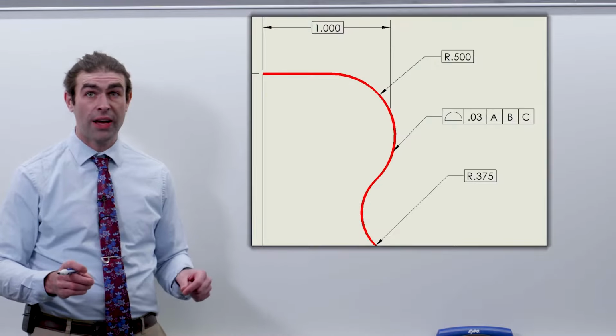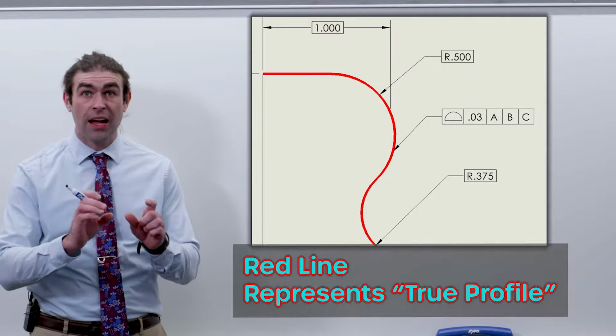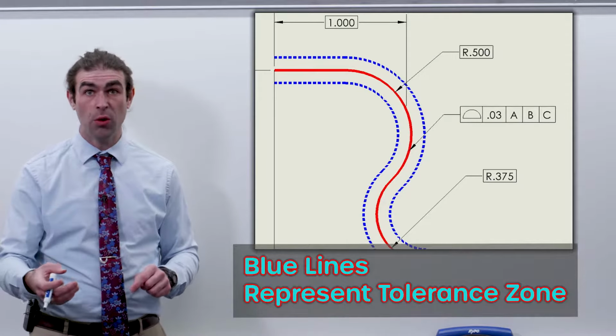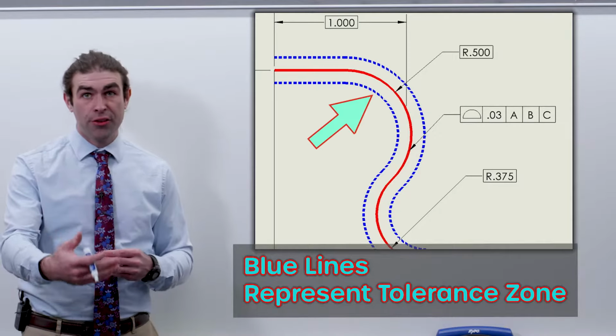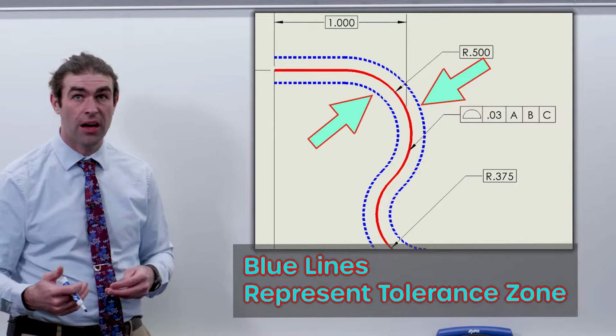The true profile is the theoretically exact place where the tolerance zone lies. So normally, if it's equal, bilateral equal tolerance zone, you got half your profile tolerance on one side of the true profile and half on the other.